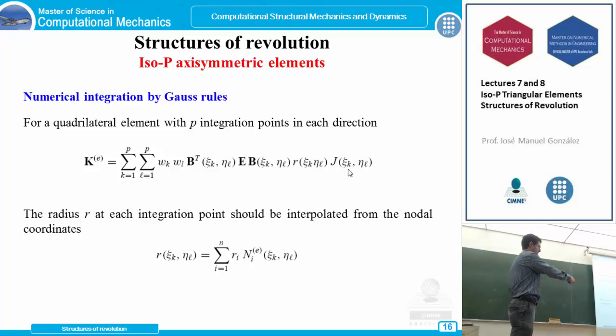Okay, so this term here, this r, which is the special guest in this development, involves first of all a geometric interpolation which changes the order of the polynomial we were used to working with using triangular or quadrilateral elements. So now we must think about which quadratures we want to use, because now the order of the polynomial, the order of this function, changes because of the appearance of this r here.